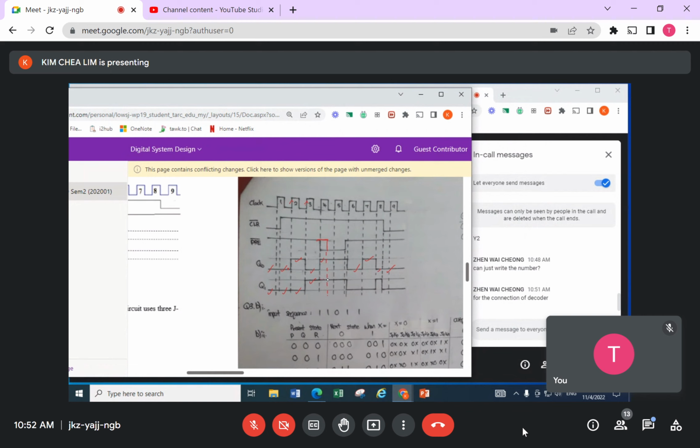Then now I realize that my preset goes low. Very good for me. Preset goes low means that preset is working, so preset makes the output become 1. So I stay at 1 until I see the rising edge at clock number 6. Then I check what is waiting in front of me. Actually it's a 1, so I toggle. Number 7, I see a 0, so no change.